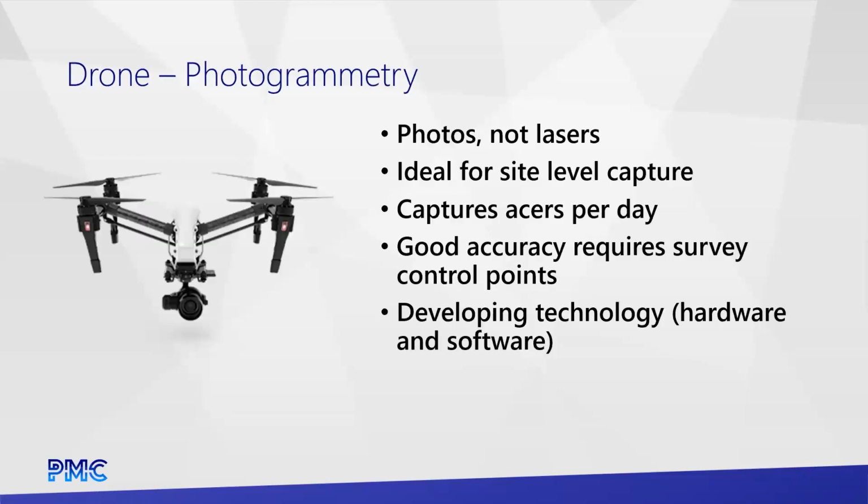Drones and photogrammetry. So you can put a laser on a drone, and we're seeing improvements in that data, in particular a solution from Leica that's better. But what I will say is I have not seen drone-based laser data that is better or even comparable to the photogrammetry data that is being produced today with the top of the line software that's out there.